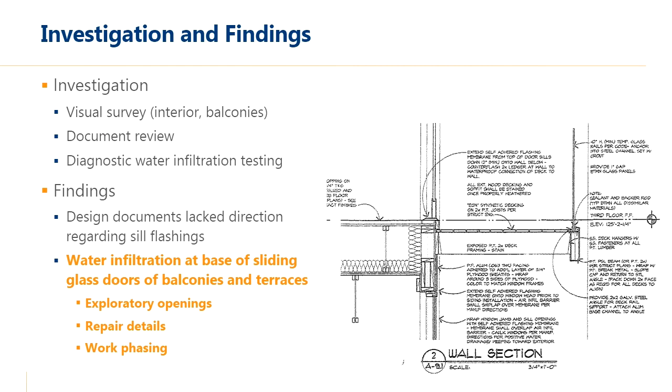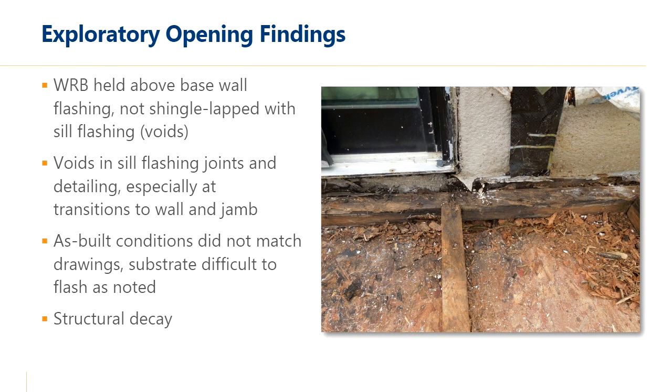Once we were done with the document review and based on the water testing, we did mention how water was getting in at these door flashings. So to conduct the repairs, we conducted exploratory openings, to verify the existing conditions and as-built, and then develop repair drawings in the hope that repairs could be completed on a unit by unit basis. We'd open an area up, we would see what we'd find, we'd develop repairs, and then implement that work to move to the next location.